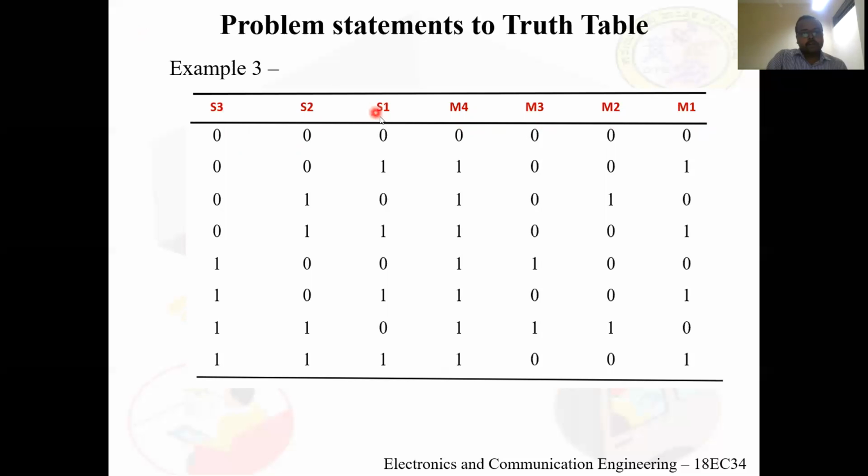Now here you can see for S1, now we have a material on the first conveyor, since it is one here, right? And the respective motor has to be turned on. Which is the respective motor? M1 has to be turned on here. And since there is a material on S1, as I said, the M2 and M3 motors need to be turned off here.